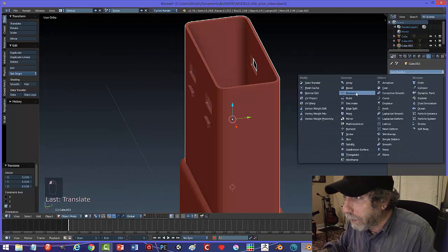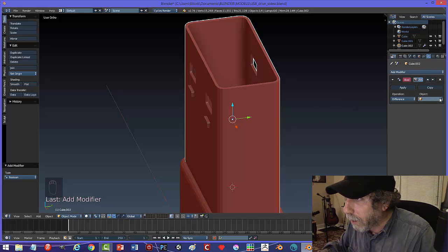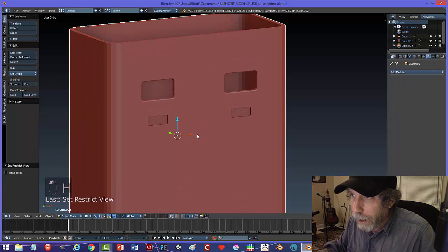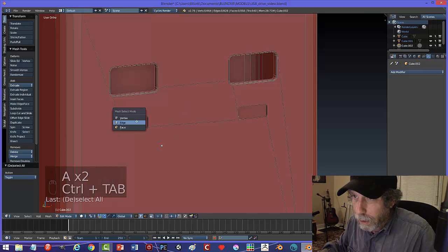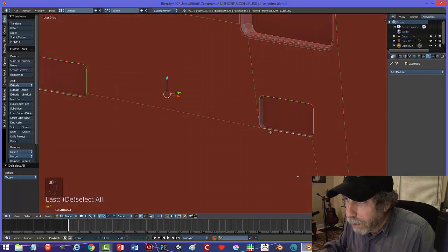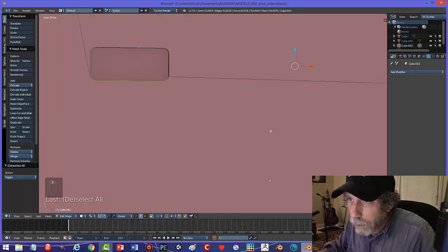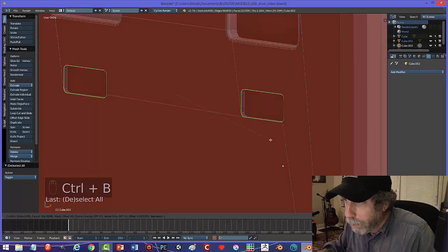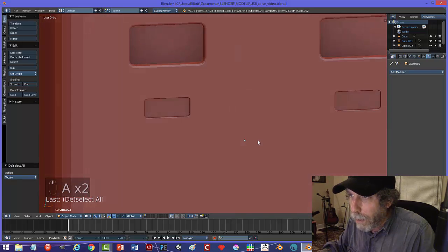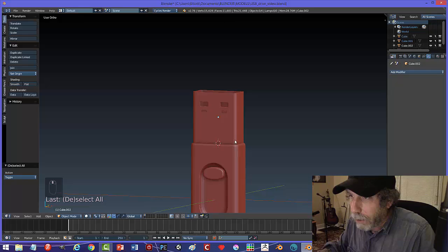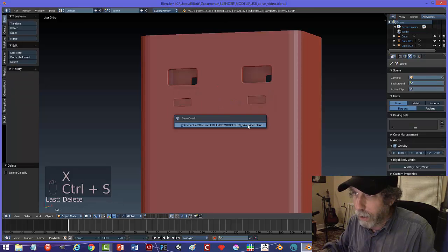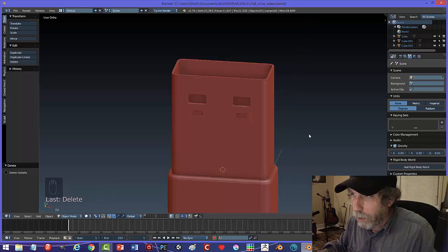Okay, so I'm going to select Boolean difference, apply. There we go, just like that. And I will do my best to select the outer edges of these as well. See, I've got to make sure I get it all. Let's give it a try. Control B, pull back. 1, 2. That's all I need to get a little bit of rounding in there. And that's how that part looks. Okay, I'll unhide those and I will delete them and save. So far, so good.